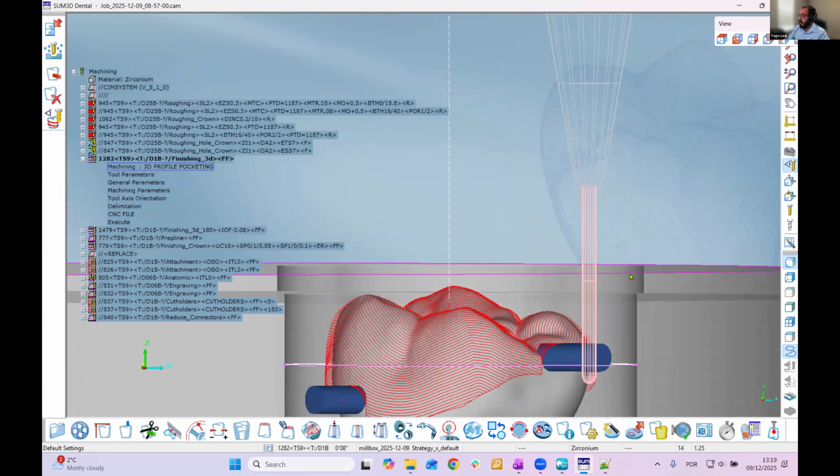Because when I'm doing the undercuts and tilting my tool, if I'm getting closer to that area and for some reason there is debris of material on that area, it might cause a tool break. So on roughing, sometimes we go back and do another pass around that area to remove any burr or debris of material that we might find, just to make sure that when we're using the tilting undercut or whatever tilting operation it is, and we get closer to this area, you don't have any material there. Some people think, oh, it's air cutting, but it's actually going back and doing that on purpose. Sure.